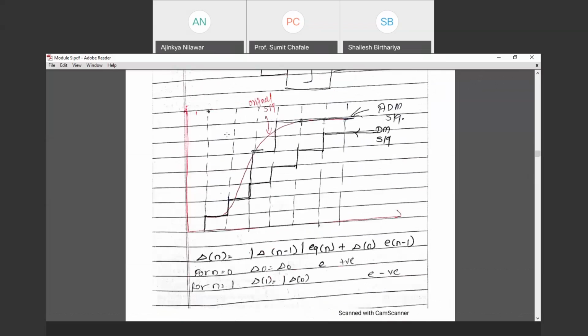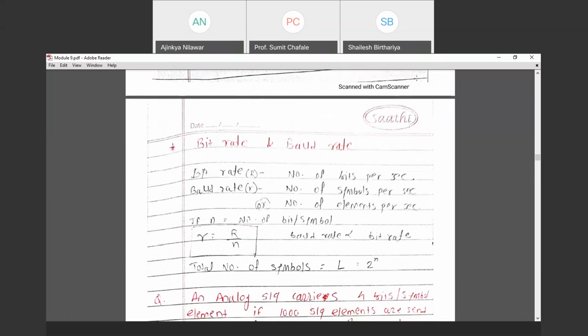So one may ask the question why? If it is fine, we are having analog communication. You are saying that it has a problem, amplifiers are needed at a certain distance. Then we came across digital modulation schemes. In digital modulation schemes also, you are saying PCM has more number of bits, then DPCM has a lesser number of bits, and then adaptive delta modulation is the best scheme. Then it is fine. We are using the adaptive delta modulation scheme for communication and we are doing the communication. Then why are we going for the next technique and the next method, that is the shifting technique.